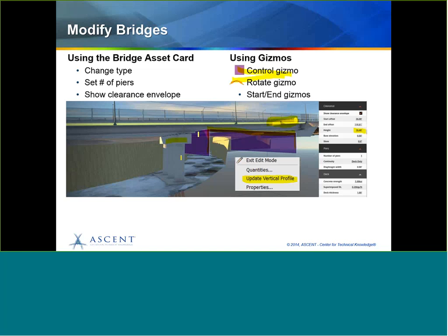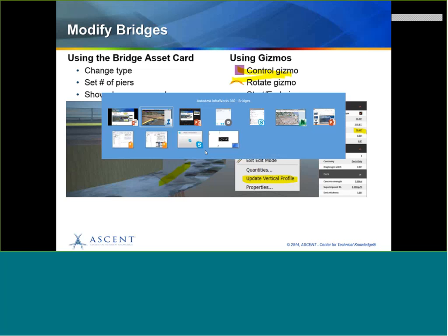So in fact, if I don't want my pier crossing my stream like it is in this image, I can rotate it and make sure that it goes along the stream and make sure I am blocking as little of the water as possible. Because again, this is going to be a whitewater park. We want to allow those paddleboarders and kayakers to flow right under that bridge without hitting into those piers. So let's actually look at how we can modify the bridge in InfraWorks.